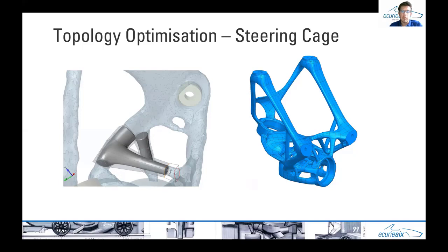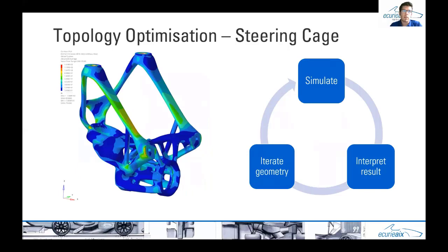After we constructed it, we go back to HyperMesh and simulate the constructed part with the assumed forces and the same connections as in the topology optimization. So that we get an idea of how the construction works, and maybe we can save some material to save some more weight.